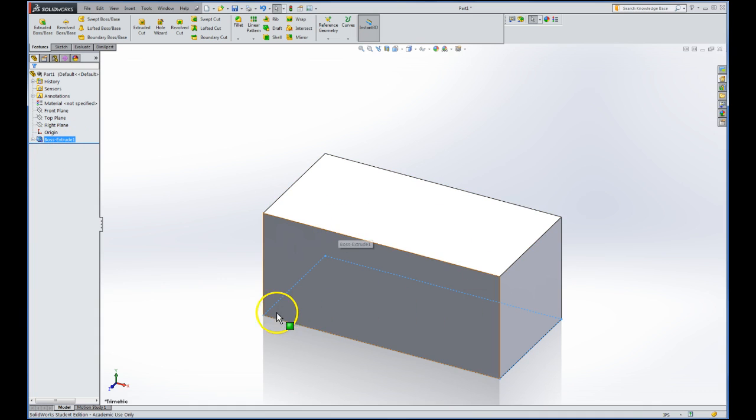The features shown here in light blue, that's the original sketch that we had. That sketch still exists. If you click the little plus icon next to that boss, you'll see sketch 1. It appears right there. If you don't want to show that, just click anywhere in the blank space, and that now disappears. If you want to show it again, click back on sketch 1.